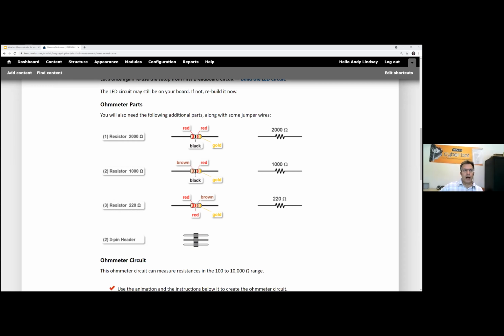But the problem with that is that the microbit is not designed to supply enough current to the servo. Yeah, and that's why we have that separate battery input. Regardless, I really love the idea of powering down the microbit like that. Thank you, Ken.